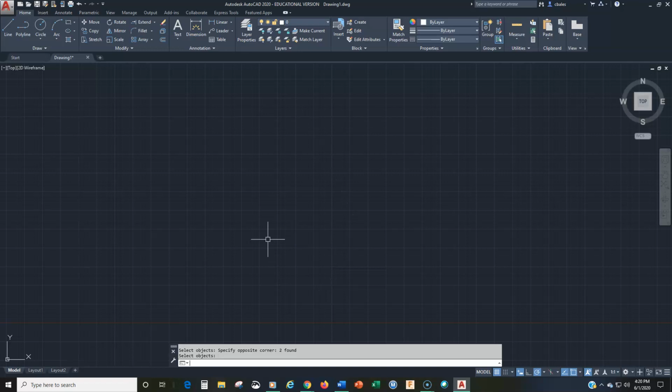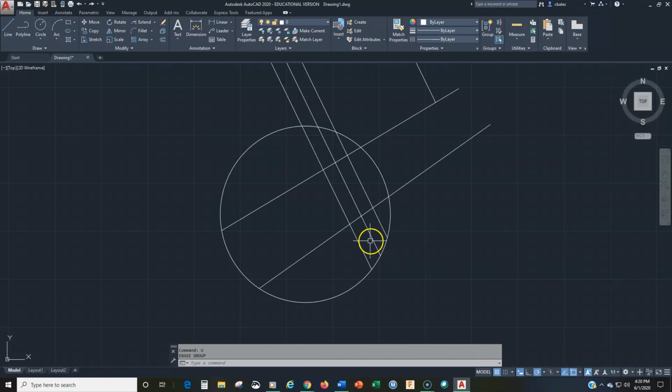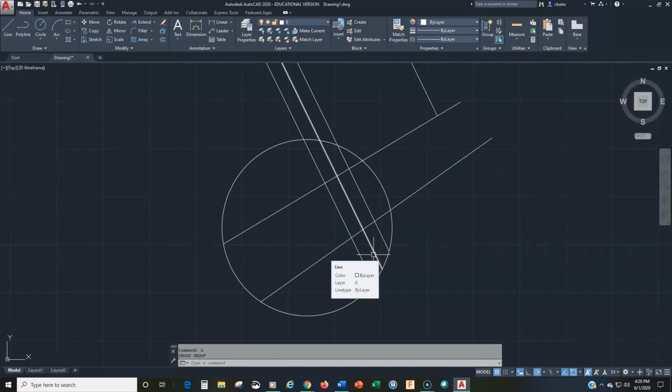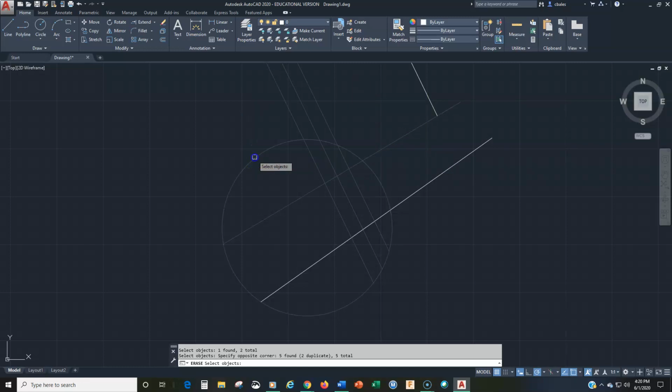And then we can erase the objects. Okay. So let me bring these back so that we have something to erase. There we go. All right. So just a couple more with the erase command. So we picked the objects, right? We can pick in space and use the blue window, or drag it to the left and use the crossing window. What other ways can we select objects that are useful for us?